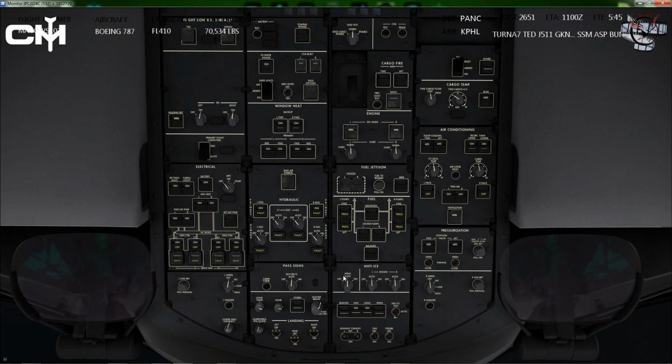Excuse me. And then the anti-ice, we leave it all in auto. And then our lights down here, we don't need runway turn-off lights, taxi lights, strobe lights. We did our tests already, just because I was trying to show you something that didn't work. This is the APU bottle discharge light that it's talking about. Obviously, it's not illuminated. I don't know why I just clicked on right washer. And then we don't need beacon or wing lights yet, so we're good to go on those.